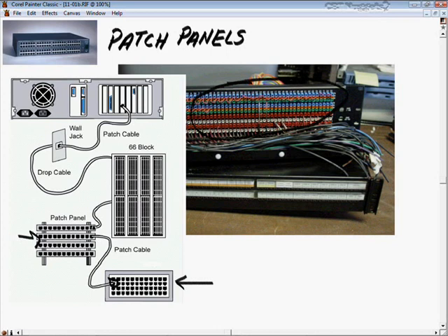And so you have bare wires coming from the patch panel to often what's called a 66 block. Now there are several different terms for this. It's called a punch block or a punch down block. It's even called a quick connect block. And it's used in a wide variety of applications. It can be used for networking cabling, but it's more often used in telephony, because you're going to take these copper wires and punch them down into these slots on the 66 block.